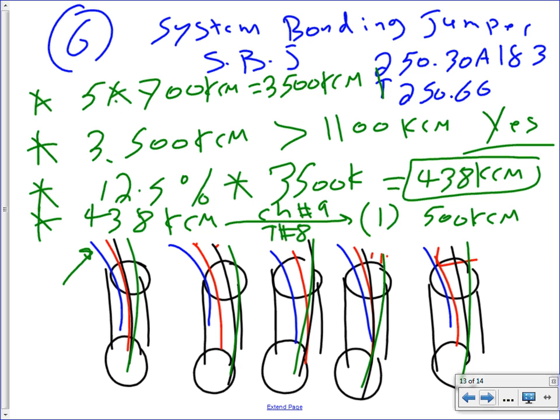I don't think we have 450, do we? We have 350, not 450. So the size would be one conductor. What insulation? THHN or bare? Typically insulated or covered at least.